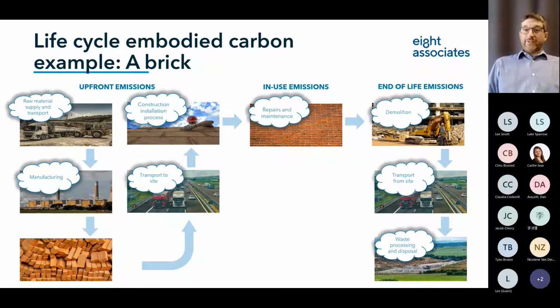But ultimately, at some point, a building will be demolished, no doubt, and then the materials can be sorted on the site. In this case, the bricks could be removed in a way that means that they're not damaged. So, for example, if they were stuck together with lime mortar instead of cement mortar, then that's possible, and bricks from older buildings are often reused. But unfortunately, some of them may not be. They might be crushed into secondary aggregates, or they may be disposed of in some kind of disposal process like landfill.